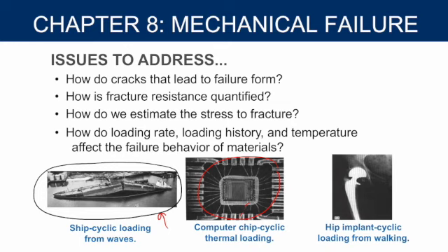The heating and cooling from turning your computer off and on, as well as the fan kicking on and back off again to keep your computer at a typical temperature, can cyclically load the wires until these small thin wires actually snap. So they change crystal structure at higher temperature. They go back to a lower temperature crystal structure. They keep doing that over and over again. Eventually, the material snaps.